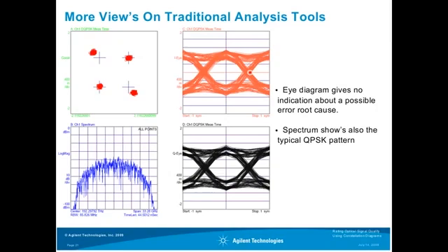In contrast, here we have a very good transmitter. Of course, it is not perfectly aligned, but we see a kind of Gaussian distributed noise. And if we look at the phase error of this signal, we can get the proof that we really have some phase error. Here the red phase is displayed on each symbol versus time, and you can see that we have a deviation of the phase error from 0.